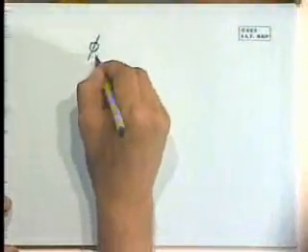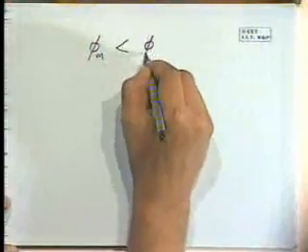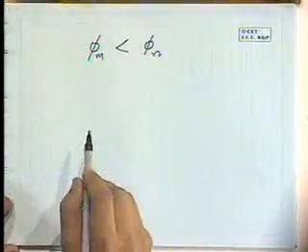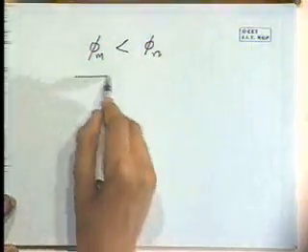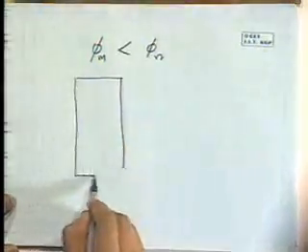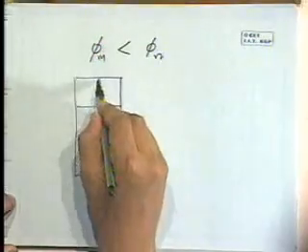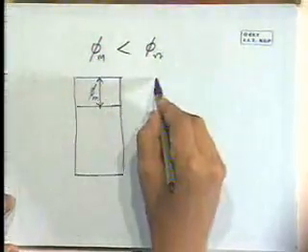And in this case, for ohmic contacts, again taking the metal semiconductor situation, in an n-type, phi m should be less than phi n. For Schottky, we saw phi m greater than phi n. In the case of ohmic, this is all ideal theory, we've got phi m less than phi n. For the metal here, we have the two of them being brought together.